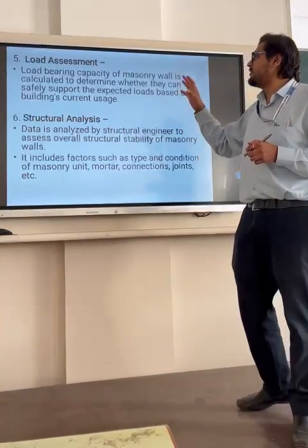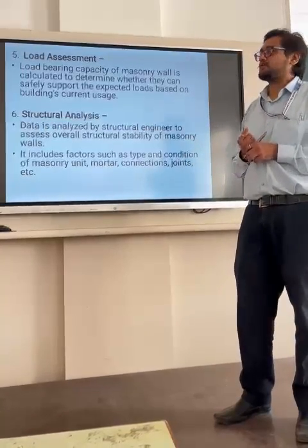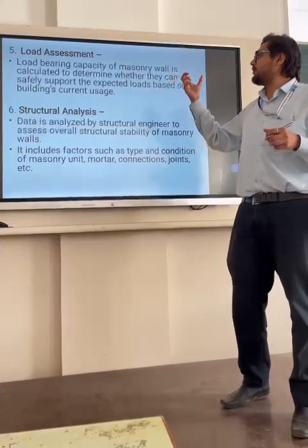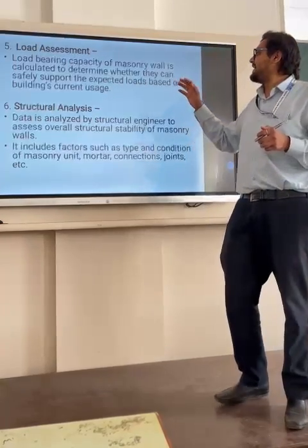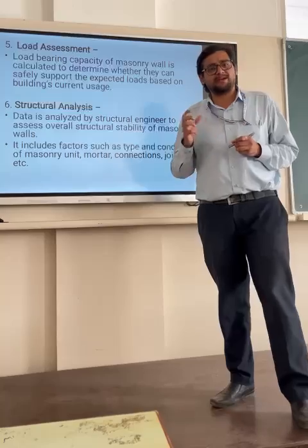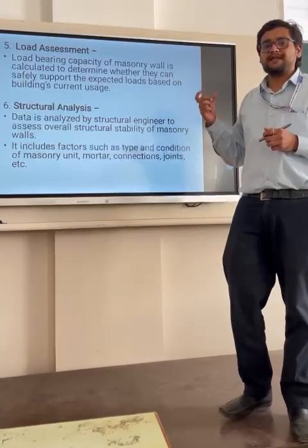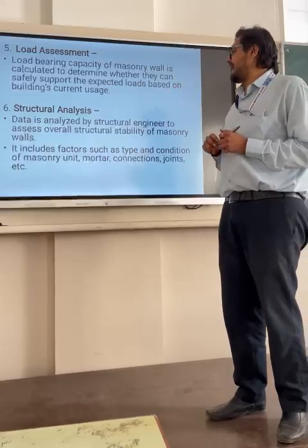Then moving further, the fifth step is load assessment. In this step, the load bearing capacity of the masonry wall is calculated, to determine whether it can safely support the expected load or not. So that strength can be evaluated by using this load assessment test.